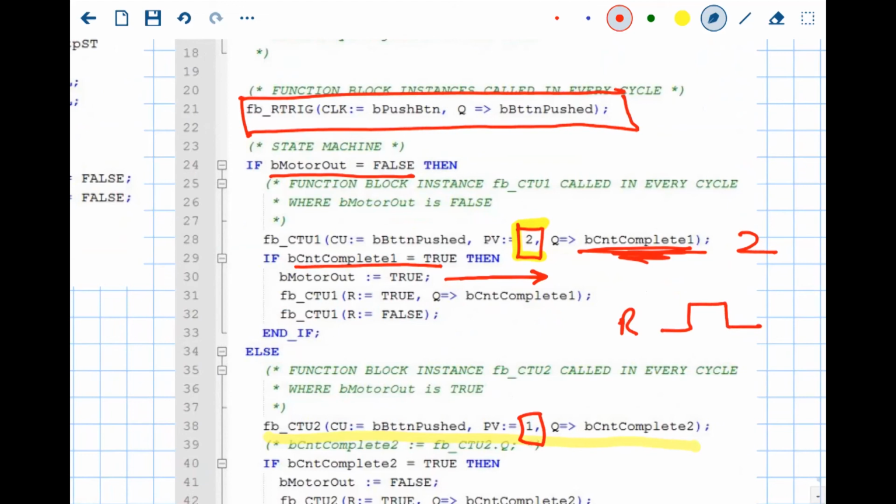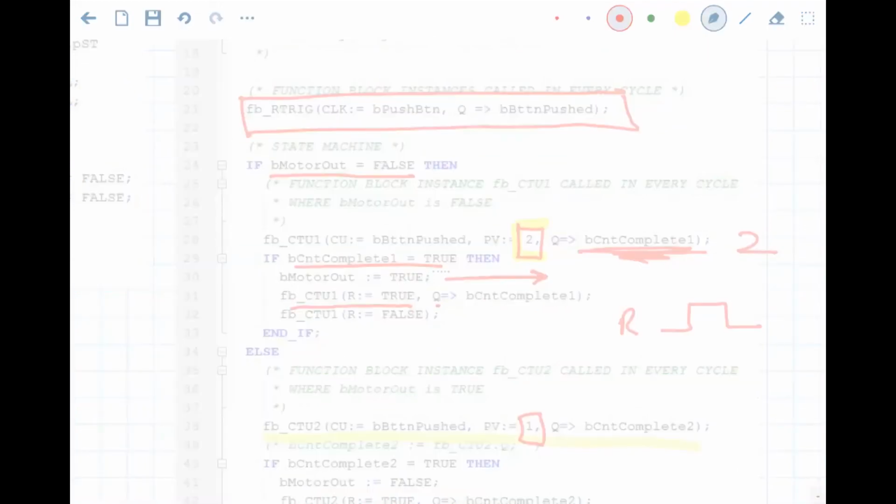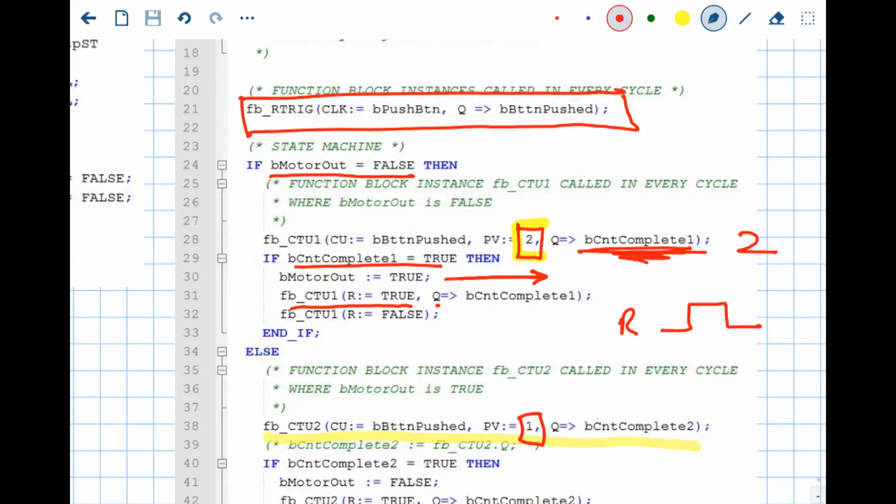So first of all, we are calling that function block again with the reset button as true. Now, one thing I forgot to mention before is that when you are calling this function block instance, you don't have to put all the input or output variables, but if you need something, you can call with that. Unlike a C or Arduino type of function where you always have to use all the parameters, over here the parameters are different. If a parameter, in this case R, is not mentioned, it is not activated. We are only using the parameter when we need it.